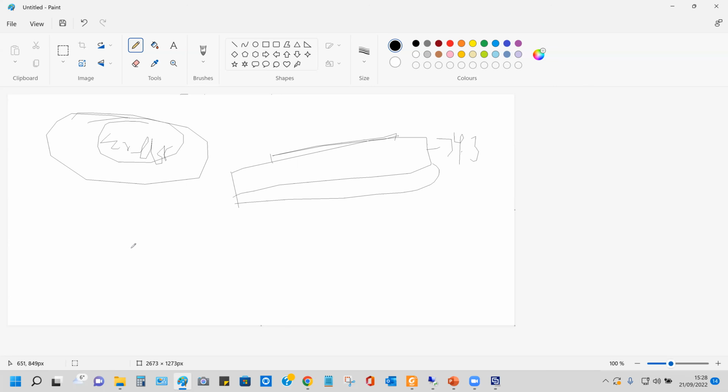So the moment you play with the epsilon r effective, what will happen to the propagation when a wave hits this? The propagation will change, because the velocity is going to change. A change in velocity means a frequency change. A frequency change means, in other words, a phase change, phase and amplitude change.